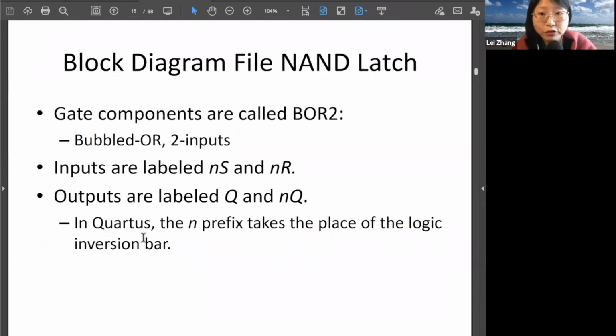They don't manufacture FPGA devices, but they provide very good design tools for the different FPGA hardware devices. And those tools are very advanced. They can give you a lot of optimization functions for generating very compact and fast synthesized and implementation results from your VHDL code or even SystemC code.